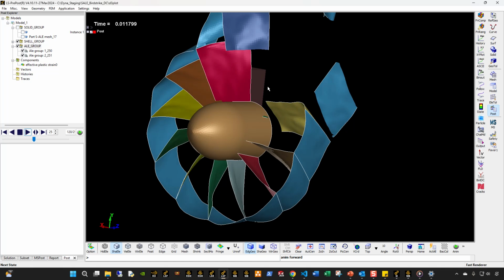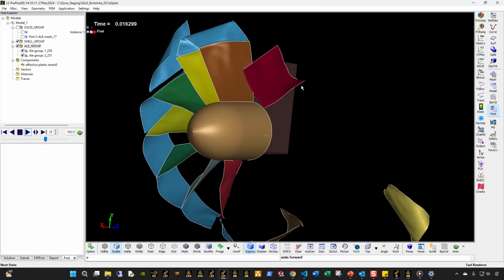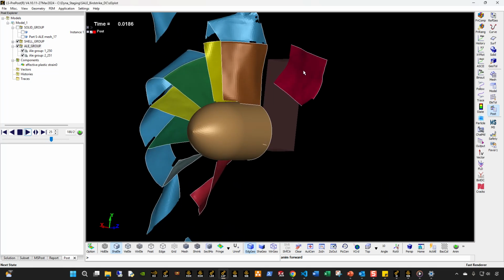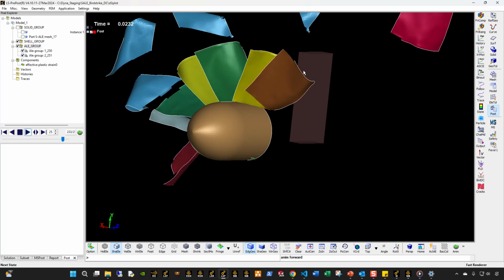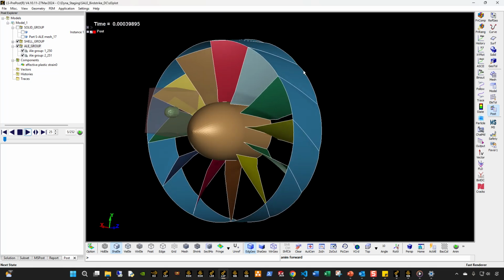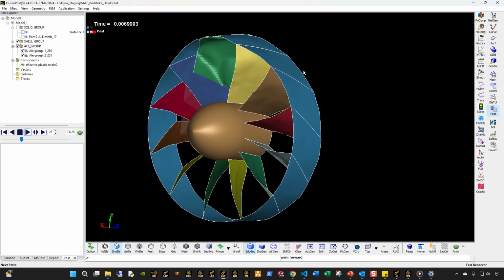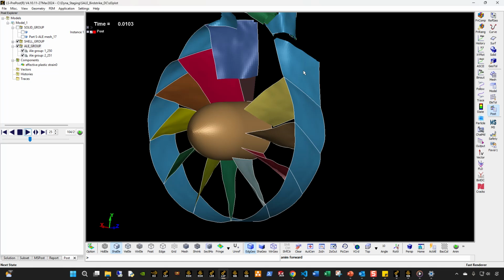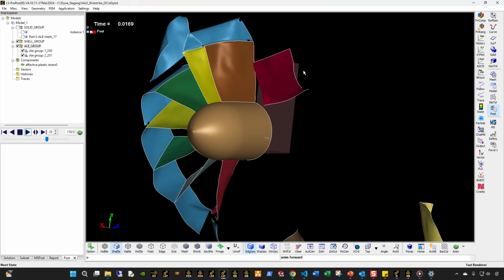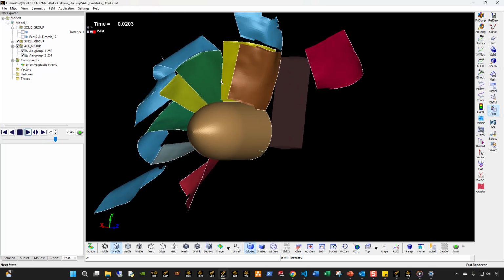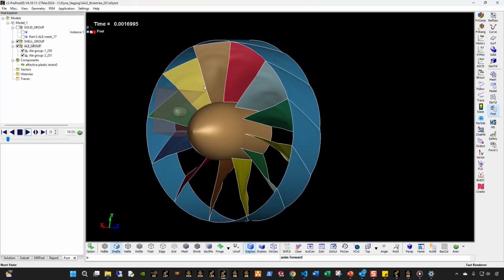And that's the beauty of an ALE model. You can model these kinds of interactions for a variety of different problems, and I'm going to keep doing other problems like blast and explosion. There are other cool things that we can do. It's a very useful technique to capture that kind of physical phenomenon where we want to model a fluid-structure interaction without having to do a complex CFD analysis. We can model the fluid behavior as a bulk response inside the Lagrangian frame, using a mixed formulation like Eulerian and Lagrangian elements, like the ALE we're doing this with.